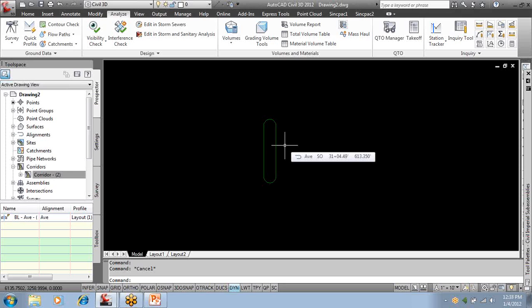So what's the difference between what you just showed here and running an alignment all the way around the perimeter curb? Unfortunately, they're quite a bit different. This would not quantify the curb for you. What this would do is say this is the length of it, and you'd have to make a quantity takeoff that says, I picked a polyline, it represents this much curb, and whatever that length is, use that. The other one automatically is an object, and it knows what that is and pulls the quantity from that object automatically. You would have to kind of say that this is a certain type of curb.